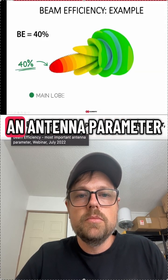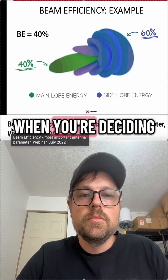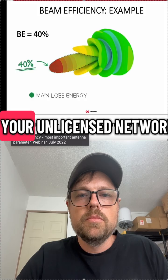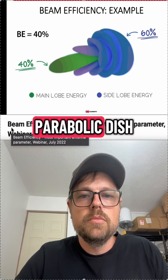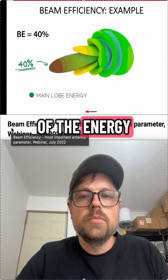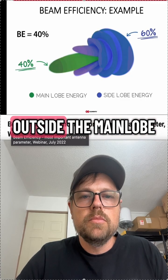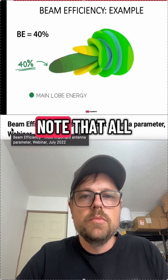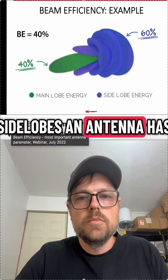Beam efficiency is an antenna parameter not only to know about, but actually also factor it in when you're deciding on how to deal with the interference issues you may have in your unlicensed networks. Now here is a practical example. So this is the radiation pattern of a generic parabolic dish. And if its beam efficiency is 40%, the remaining 60% of the energy goes everywhere else. In other words, side lobes. Because any radiation outside the main lobe is a side lobe, well, obviously it must go in the side lobes. Note that all the side lobes are highlighted here, so beam efficiency includes all the side lobes an antenna has.